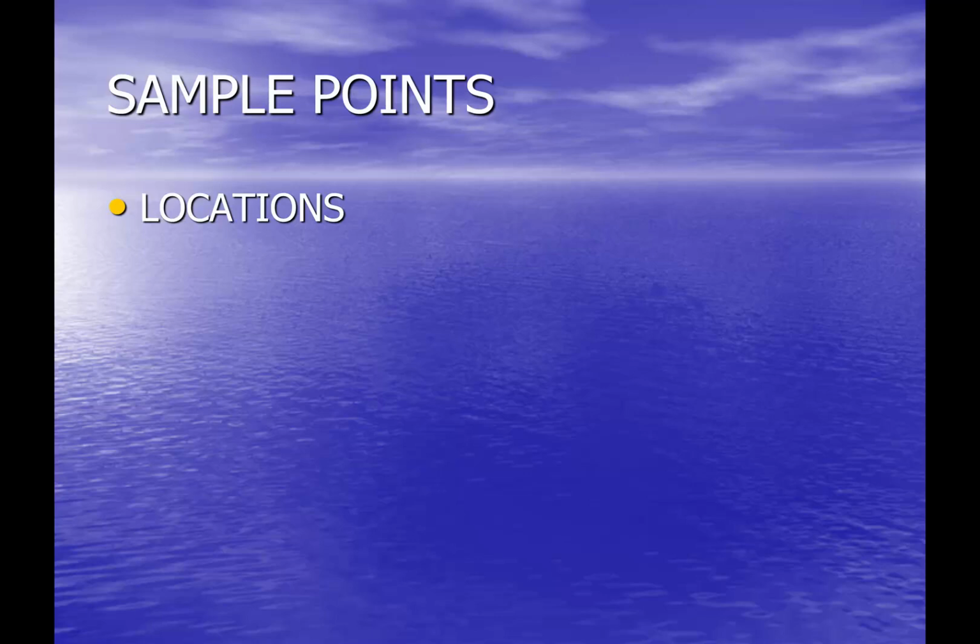Those are the dedicated sample points. As we talked before, we'll also have upstream and downstream sample points for each one of those locations. We also pull samples from our storage tanks, from all of our sources of supply. We do weekly, monthly, quarterly tests, literally thousands of annual tests to demonstrate compliance.